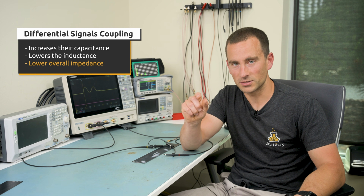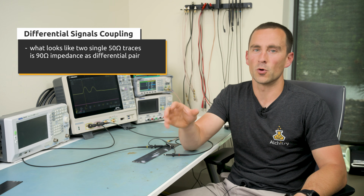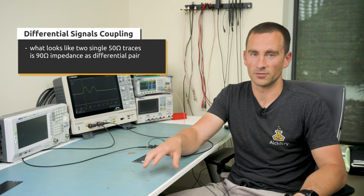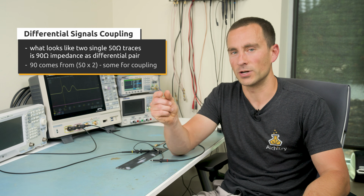Depending on how close the traces are, you may see that what would be two 50 ohm single-ended traces would have something more like 90 ohms of impedance when used as a differential pair. The 90 comes from doubling 50 to 100, and then the coupling of the two traces subtracts a bit off of that.